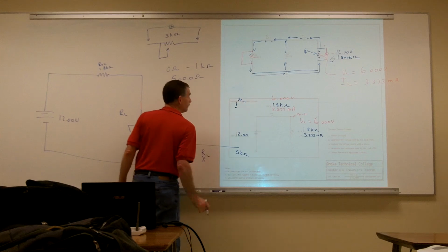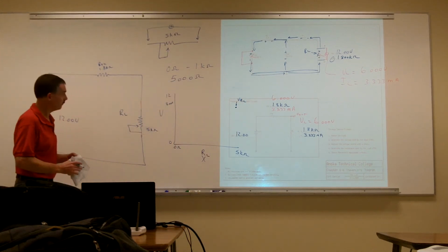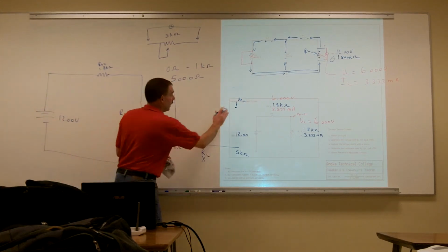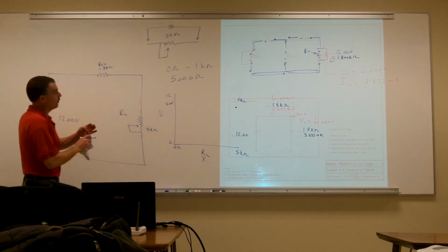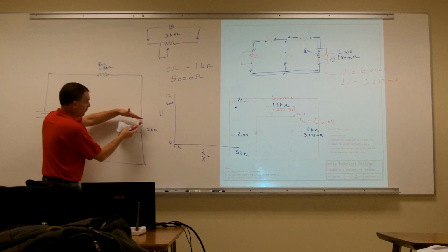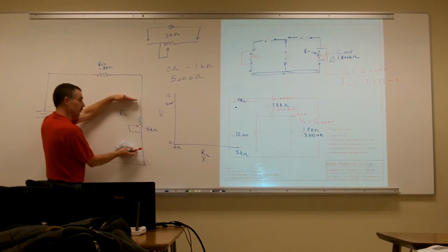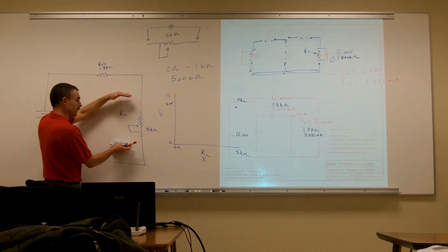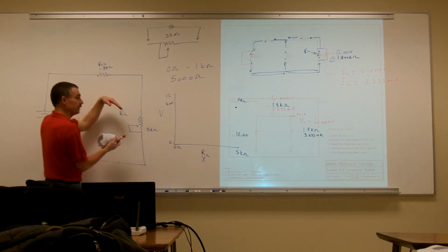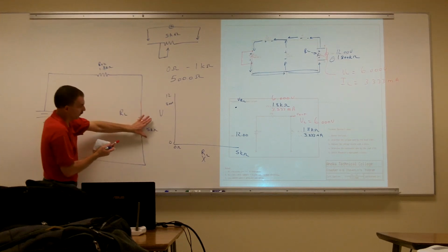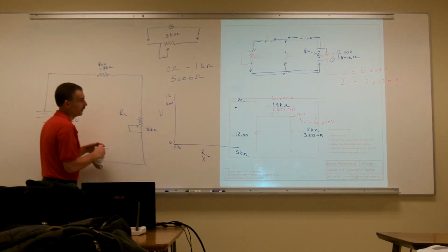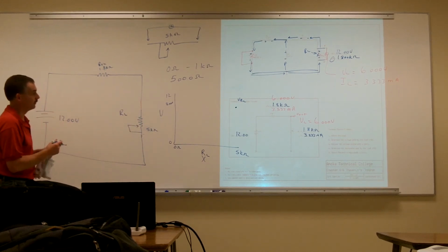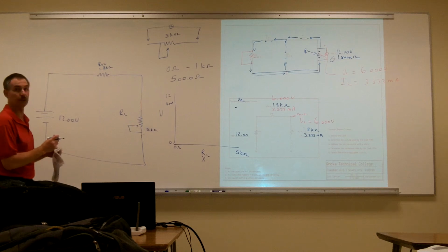Voltage of RL. Okay? It was... so now with my having my maximum amount of resistance in this circuit also, what happened to my current? Is it increased or decreased? Before it was 1.8 kilo ohms, now it's at 5 kilo ohms. So what happened to my current? It decreased.